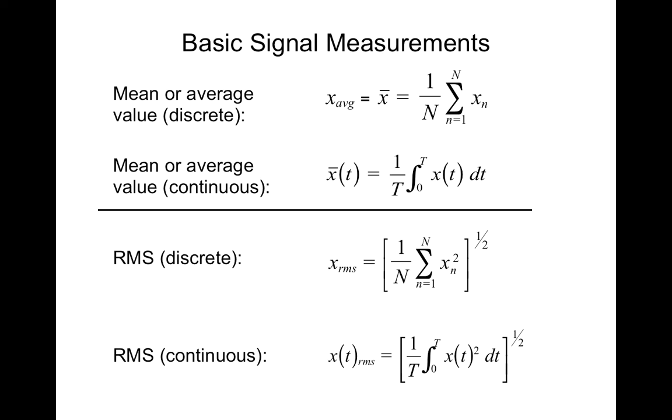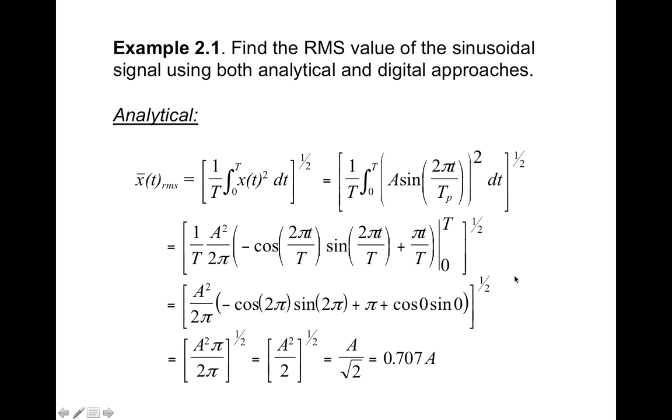So what an RMS value gives you, sort of an analogy, is the effective DC current that would generate that same power level. And for a sinusoid, that's just the magnitude of the sine wave over the square root of 2. For a more complicated signal, we go basically to the formulas for RMS.